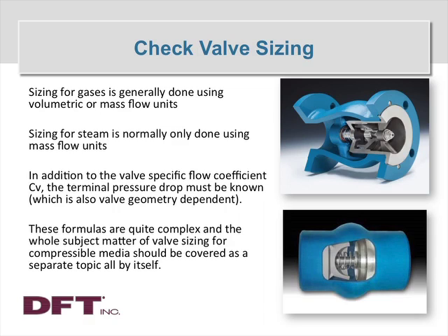The formulas themselves are quite complex, and the whole subject matter of valve sizing for compressible media really is a separate topic all by itself, and it's not my intent to give you, in this 1-hour course on check valve sizing, everything you might want to know about sizing valves. That's probably better done in a one-day seminar, or maybe even a college semester type course. But suffice it to say that you're looking at a far more complex situation, because you have to take into account the compressibility of the gases at the temperatures and pressures that you're dealing with.